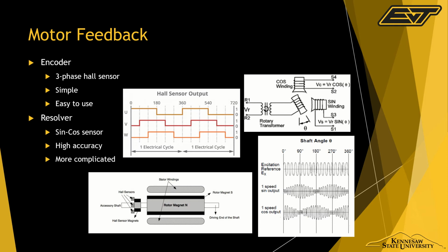In order to have magnetic induction, you have to have a moving magnetic field. So if the motor's not running with a permanent magnet, then you're not going to see any voltage out on the cosine or sine sensor, which means you're not going to know the motor position from startup, which can be kind of bad. So maybe those don't exist. I don't know. But from what I found on the internet, this kind is the most common.